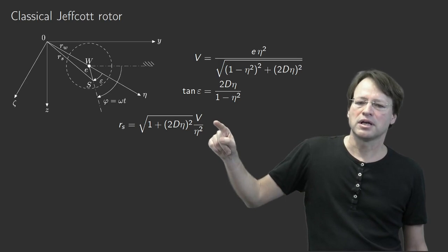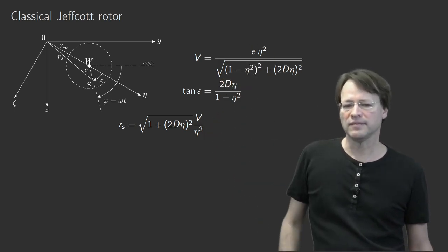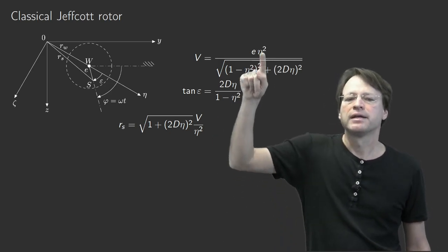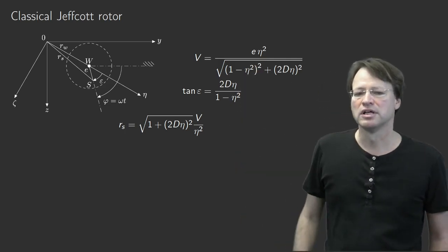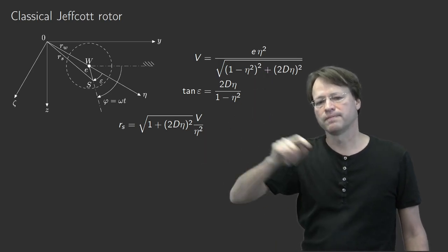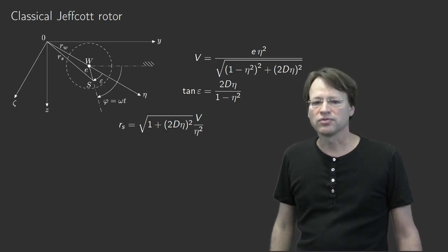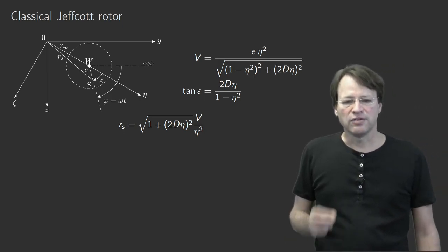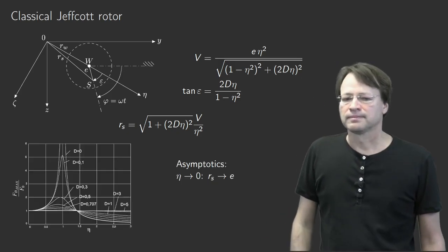And if you take into account that that magnification factor is not the classical one for a force that acts directly on a mass, but it's the magnification factor that is modified, in the numerator, by the term E times eta squared. The eta squared goes away, and then it's just the E we have here. This looks familiar to you. It's a classical result we obtain for vibration isolation, for active vibration isolation.